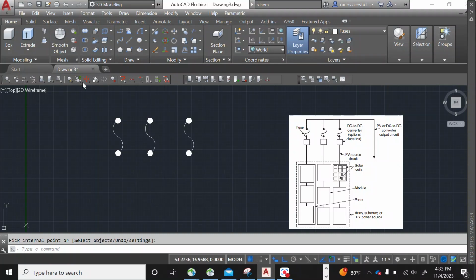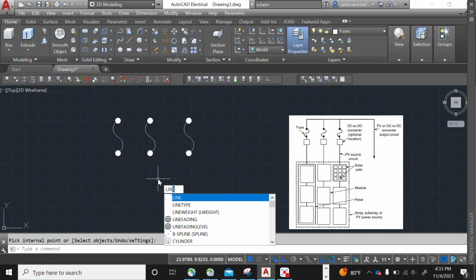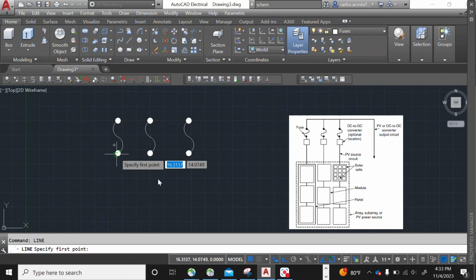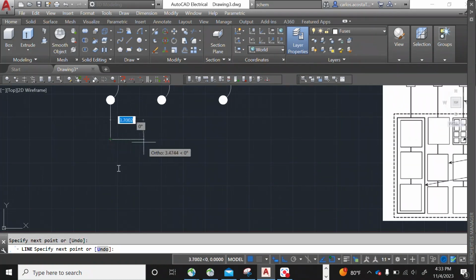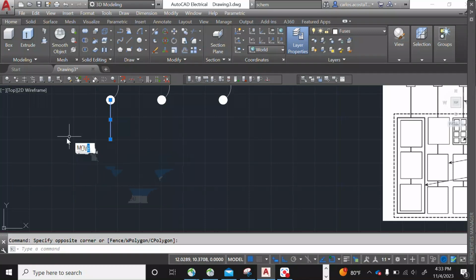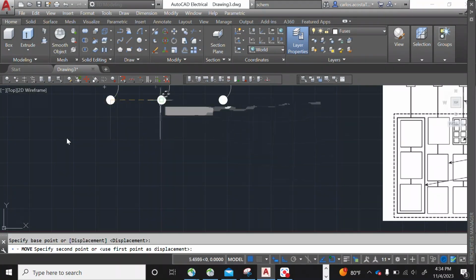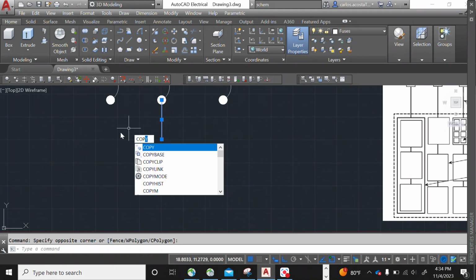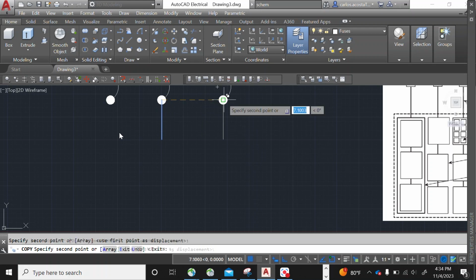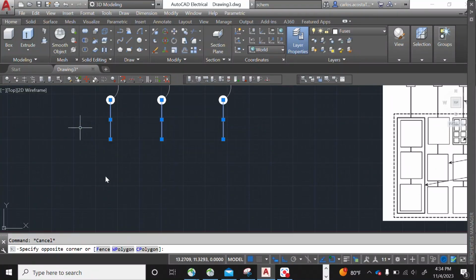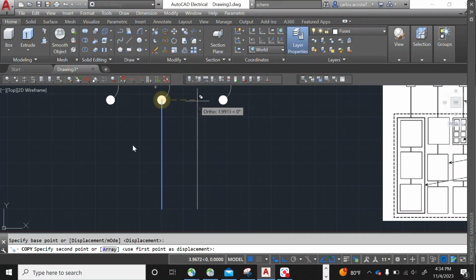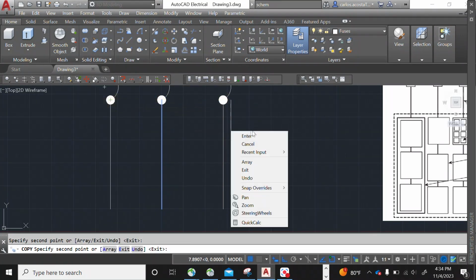Okay, next one is rectangular, so that should be pretty easy. Let's create a line so that we more or less know where our center point should be. Line, and remember that all of this could be different layers, but I'm using the same layer because I'm going to use the same thickness. So copy from here to the center point, to the center point. Okay, we have two options: either start there or do a rectangle and then trim it. Let's try that. So I'm gonna extend my line a little bit, and you'll see why.